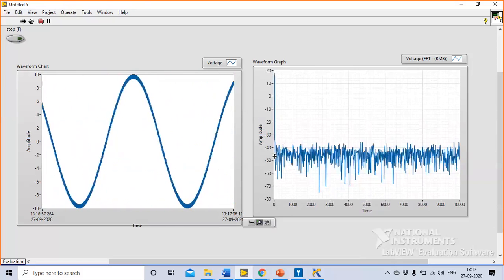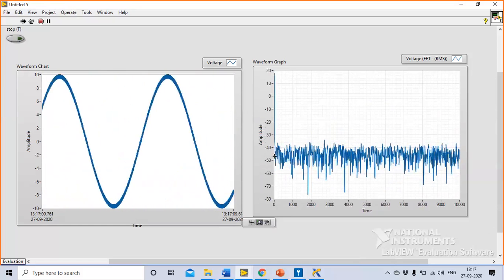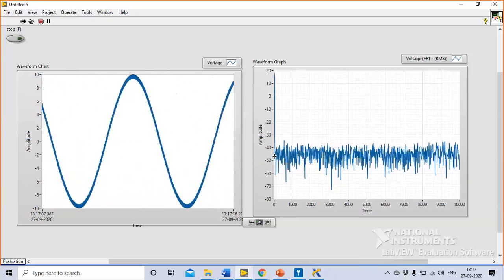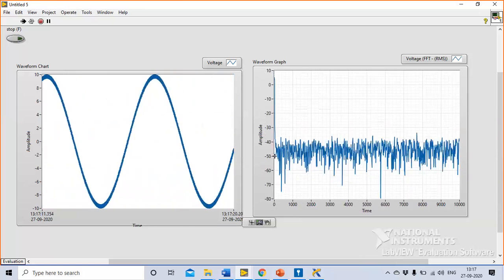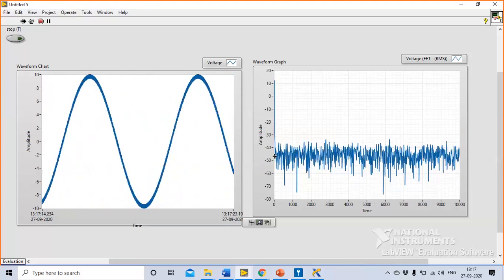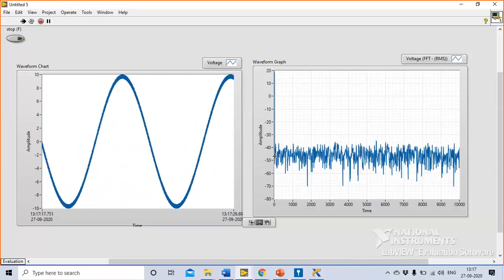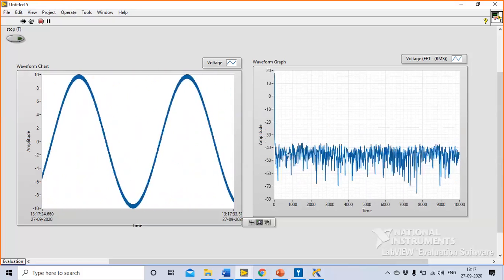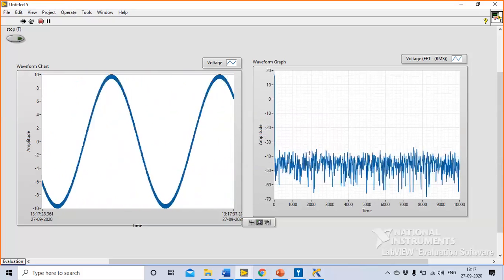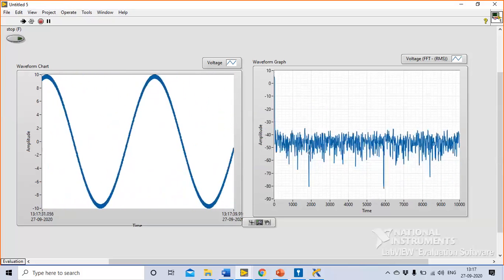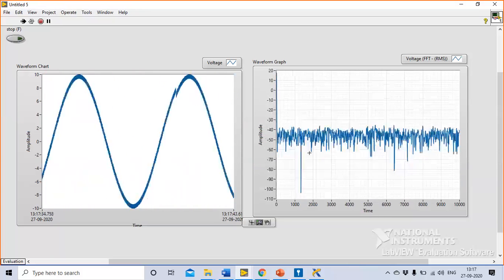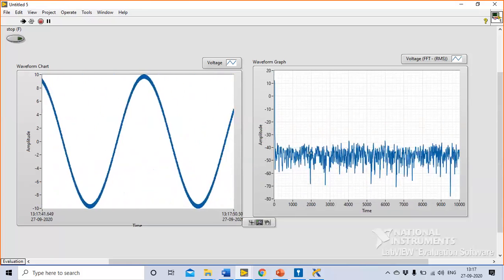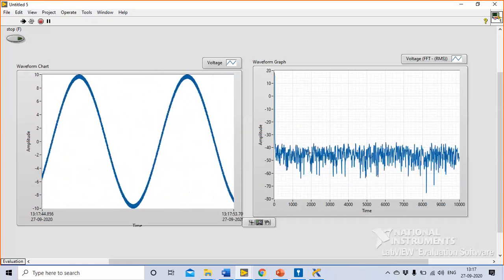When you work in industry, like a day before yesterday, there was a satellite being tested in a thermo vacuum chamber at Space Application Center. I received a call saying the system seems to be performing in an erratic manner, showing a lot of ringing noise on the signal. I asked them to plot a spectral graph and we figured out that the noise was at 50 hertz. We saw a peak at 50 hertz, whereas our signal was of few hertz, let's say 10 hertz or 5 hertz. What does that infer? That infers it is picking up the noise from your power lines.